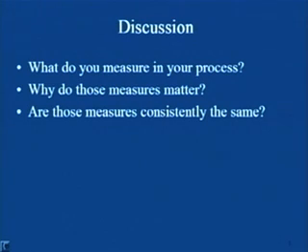When we say consistently the same, this means whether the equipment or measurement tools we are using are the same, or are calibrated, or the method used to measure is the same, or the operator uses the same method consistently, the first time and every time. If yes, good. If not, then we should know why these measurements are not coming out the same.